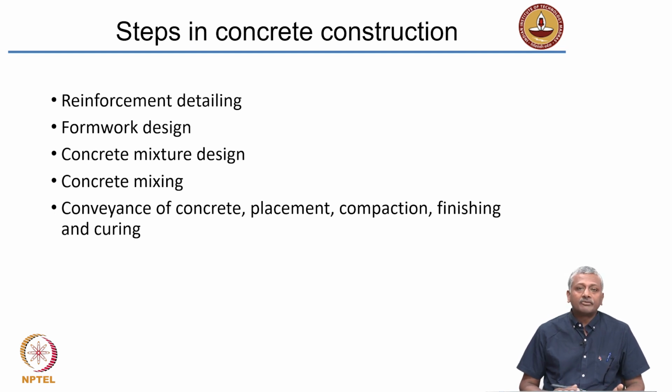And then finally, after mixing, the concrete is conveyed to the site. If it's far from the site, it needs to be conveyed with the help of trucks, for instance. After it reaches the site, it is then delivered or placed, then compacted, finished and finally cured until it reaches the right level of strength. So these are the processes that are involved. Let's take a closer look at each one of these processes.